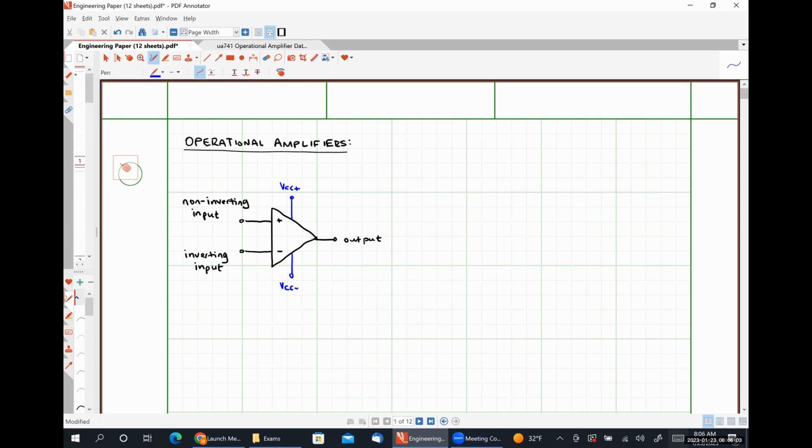So an op amp is an example of what I'm going to call an active circuit, where an active circuit means it requires external power in order to function properly, right? So resistors, capacitors, and inductors are passive circuit elements because they exhibit resistance, capacitance, and inductance regardless of whether or not they are connected to anything. An op amp can only amplify signals if power is provided to the amplifier circuit itself, okay?